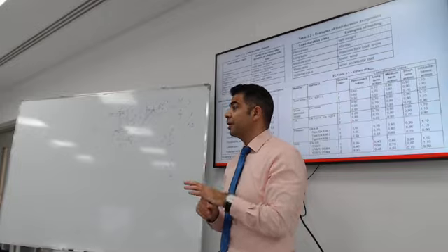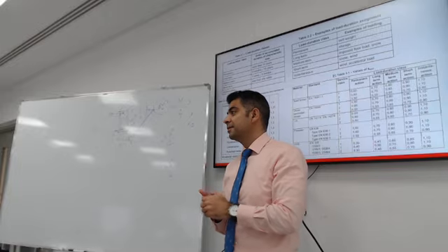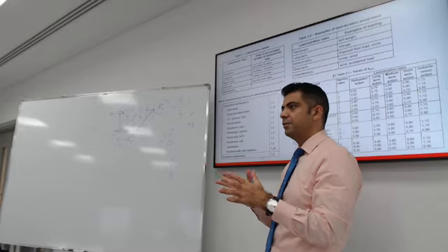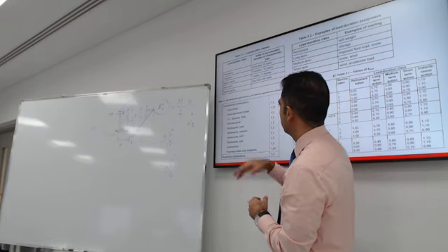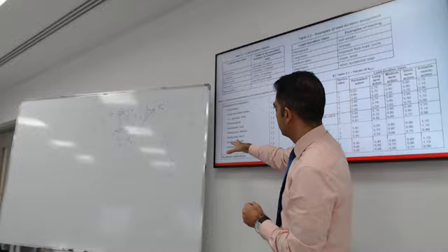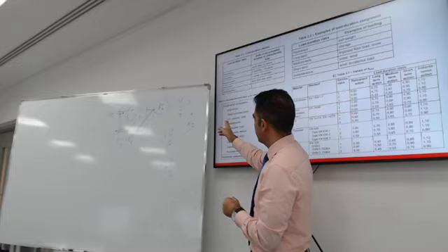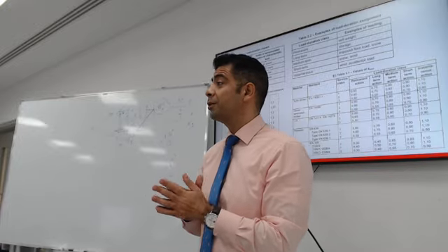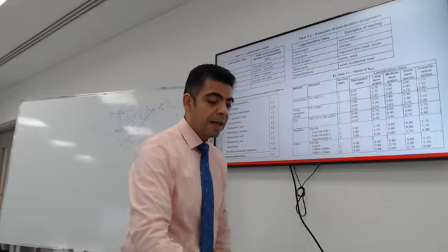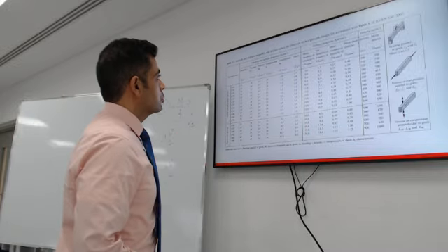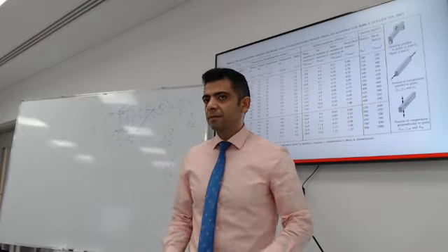1.3 is very different from 1. It's multiplication, so it's a less than 1 value. That's exactly it. So you're actually using around 70% of the strength of the material. Pretty much the same thing for these different types of fiber boards. If you're using the LVL, it's 1.2, and this is going to be the Eurocode table that we will refer to for gamma M.